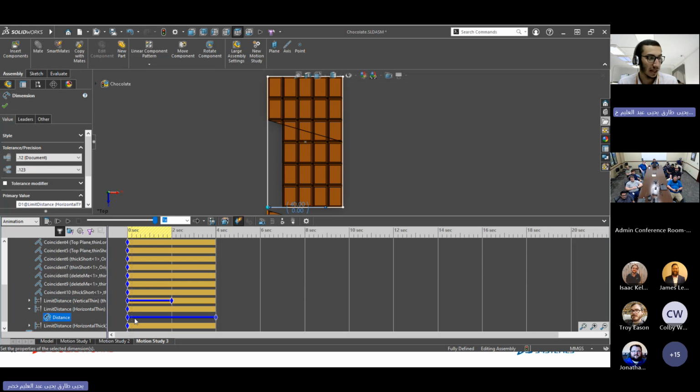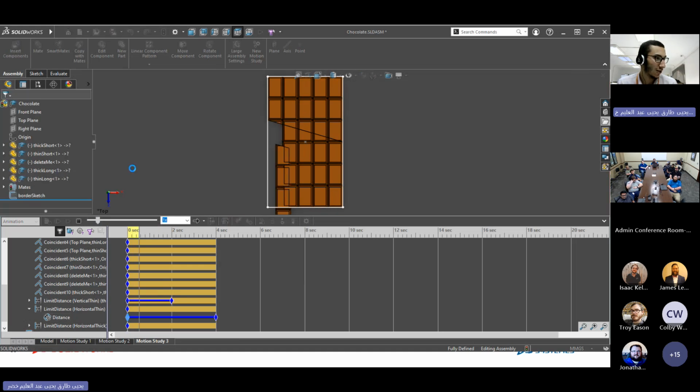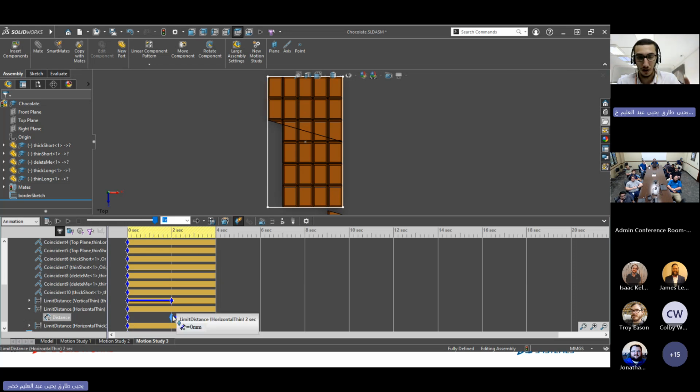And I also have the same thing, a change bar going all the way from 0 to 2, to 4, sorry. In this case, I can do the same thing, just drag it from 0 to 2 to make sure that it only starts moving when it goes from 2 to 4. Because remember, if I do this, it's going to try and do like a diagonal motion through the model like that. You know what? Let's see actually. So calculate, you see that diagonal motion? I don't want them to happen simultaneously. I can if I want to, but I've got full control. So I want it to happen one after the other. Okay, just like a waterfall or something.